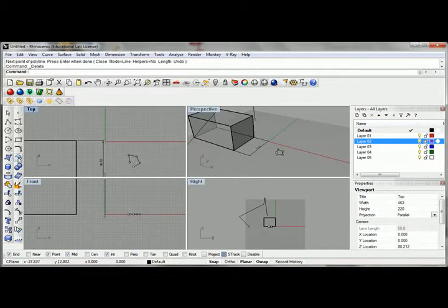And then the last component here is the two main toolbars. There's a lot of stuff here. It's essentially organized in a way that builds up. Rhino's a surface modeler, so it starts at the rudimentary point scale, and then works its way up, so you have points, and then you have curves that are comprised of points. These are either weighted points or they're literally polylines that are 1 degree curves built around that.